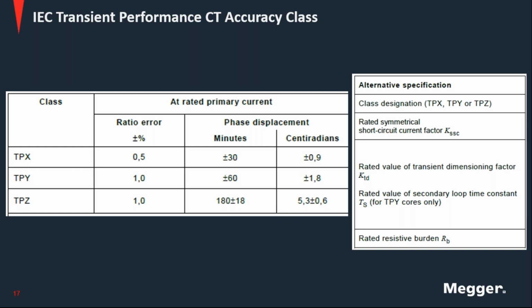So you look specifically at the resistive burden, not at the DC characteristic of the burden, not the inductive part. And these are parameters that need to be calculated from the results and then compared to the characteristics of the CT. So when you test this type of CTs, the software needs to calculate these values. That's part of the assessment in these instrument transformers.